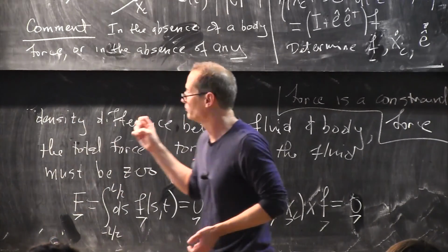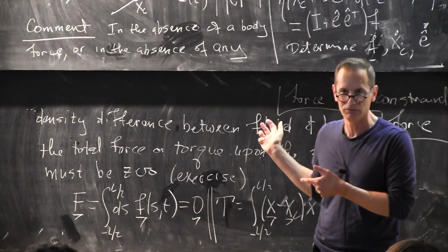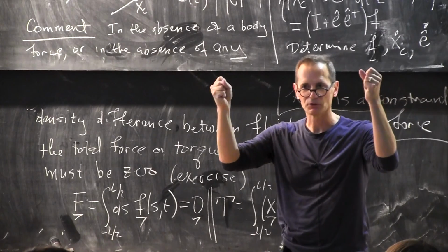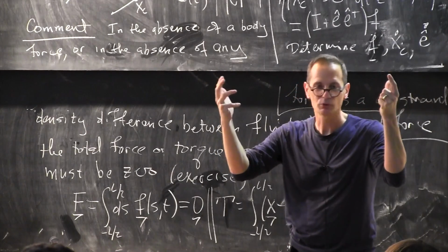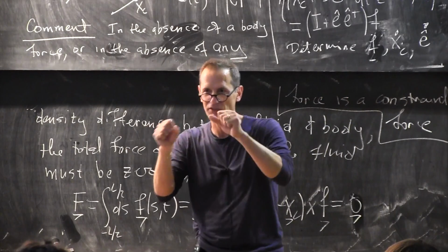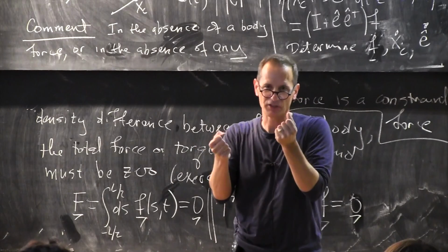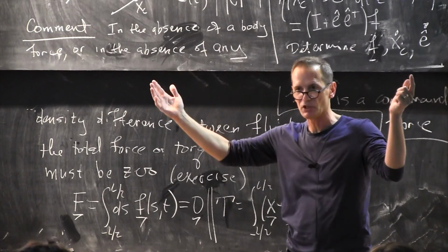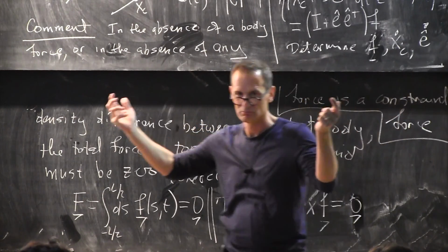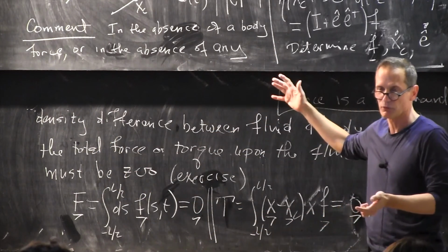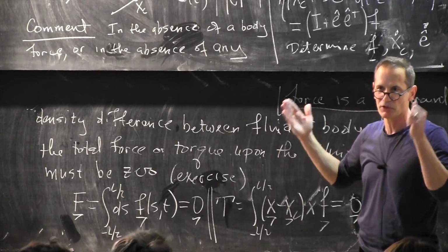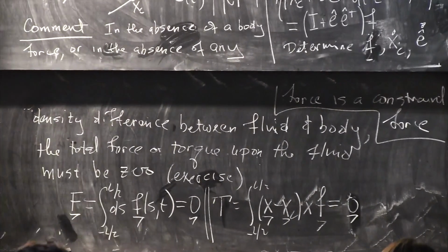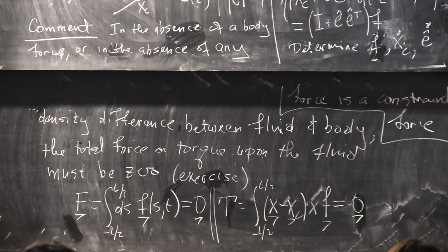So there's lots of cases where this is an interesting problem to solve. Why might it be interesting? Let's say that I have a wood pulp suspension where the fibers are really rigid, so I can treat them as straight, right? I just ignore the bending rigidity. I just say they're straight and inextensible. Then this is the formulation you would have, where this U would be the flow that might be generated by the other fibers moving around. And so this is kind of the basic piece you have to get. You have a fluid mechanics problem where all the forces you're determining, because your particles are rigid, are constraint forces. Of course, you might say, oh, big deal, many solid particle suspension dynamics problems look like that. Well, yes, that's right.